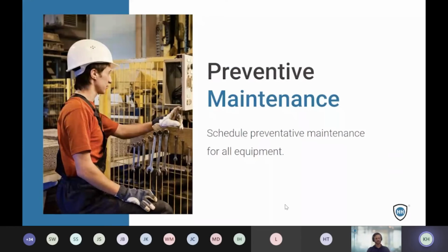When tools and machines break down, they tend to release fluids, and those fluids tend to be oil or petroleum based. So having a preventive maintenance schedule can really help you to prevent those breakdowns from happening. If you keep your hoses in good condition, keep your machines and your tools in good working order, and you're routinely looking at those things to make sure that they are still serviceable and still working within the parameters that they're intended, that can help you prevent those leaks, drips, and problems that happen when something does break down.